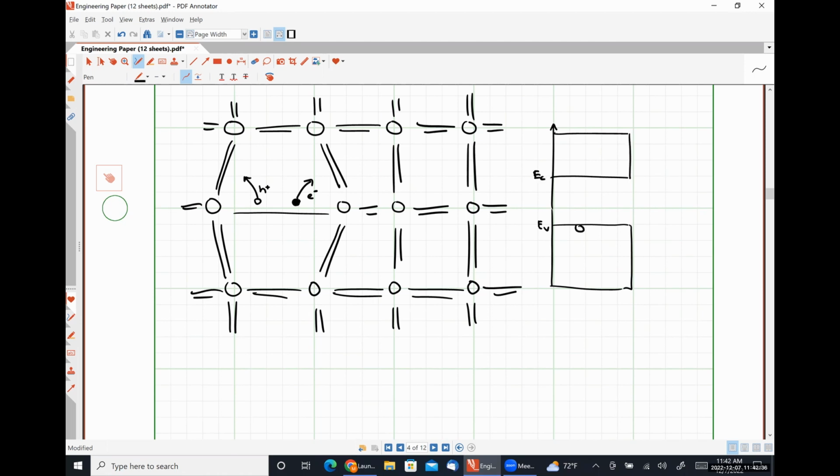And we'll see that a hole is left behind in the valence band, and an electron is energized up into the conduction band, and then it will move around through different energy states until effectively settling at its lowest possible energy position while still in the conduction band until it meets the location of the hole, at which point electron hole pair recombination will occur and the electron hole pair will have been terminated. Okay, so that process of the electron hole pair recombining is what's called recombination, hence the name.